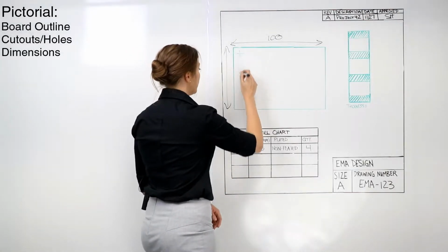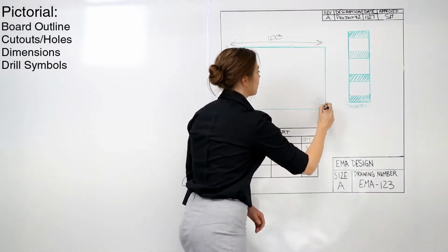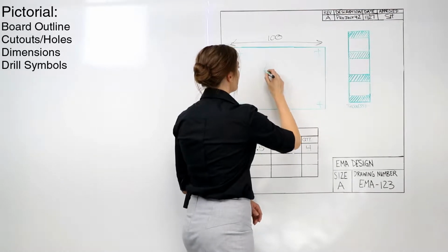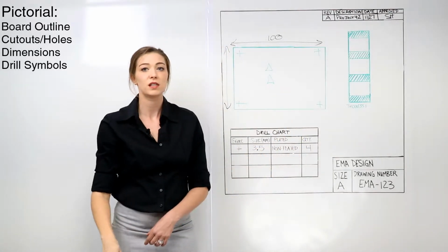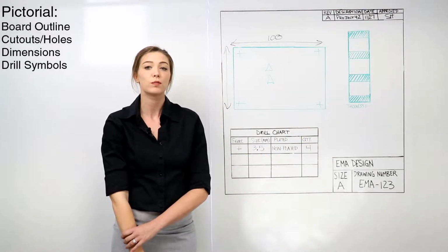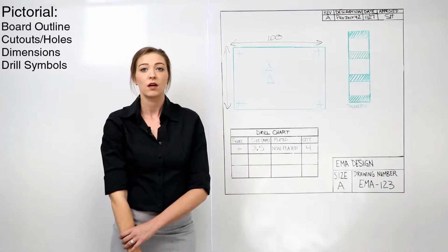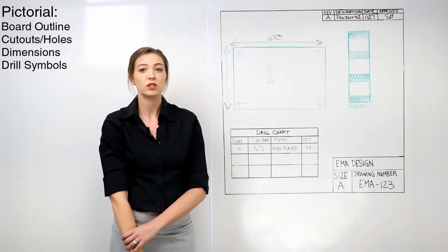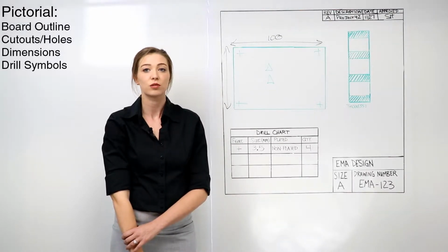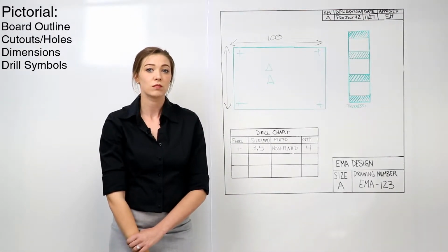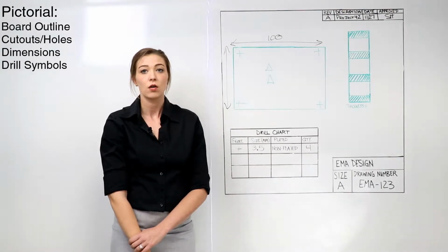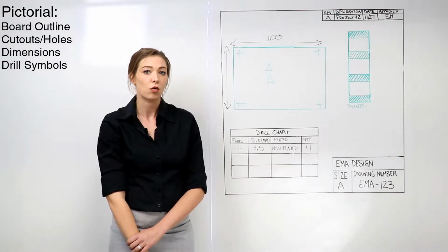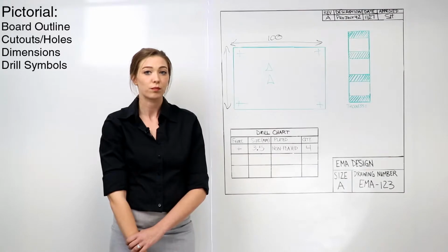Hole positions should be marked on the PCB with drill symbols. These are shapes and letters generated by the PCB software to graphically show a hole's position on the PCB. Always use a unique symbol for each type of hole. Drill symbols should be duplicated for holes containing the same attributes. If there is a different attribute, such as plated versus non-plated, or a different tolerance associated with a hole, be sure to use a different symbol.